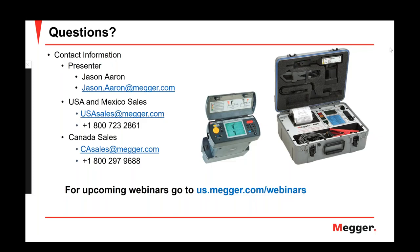All right, thank you. Sanket, how long does it take to get a stable impedance reading on the BITE 2P and BITE 3? The time differs for each measurement, and one of the reasons is the way the test is done. When you test with the BITE 2, you are injecting the current continuously throughout the string, and you take voltage measurements across each cell. So the measurement time is a little shorter.